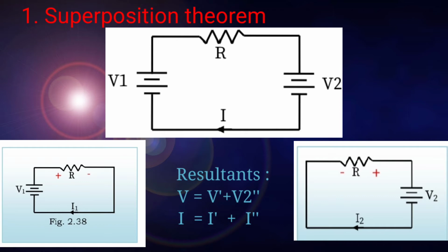Okay, here we can understand this simple network. There are two sources, and these two sources are acting simultaneously, and it is very essential to calculate the resultant current or voltage through a branch when each source acts independently. Finally, what do we do? The final consideration is what? The sum, I mean to say, the resultant. We are going to take the summation, that is, the contributions of each independent source will be considered.